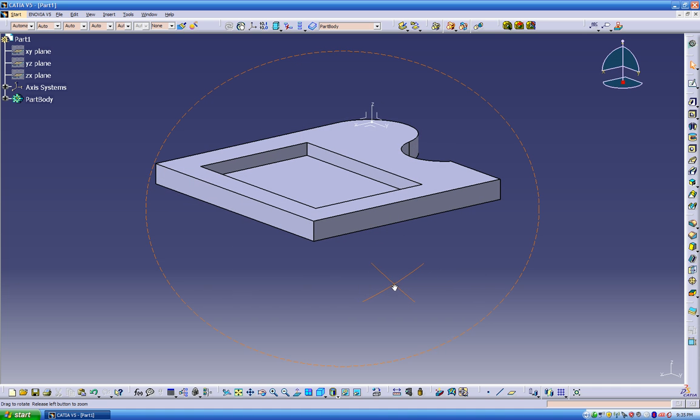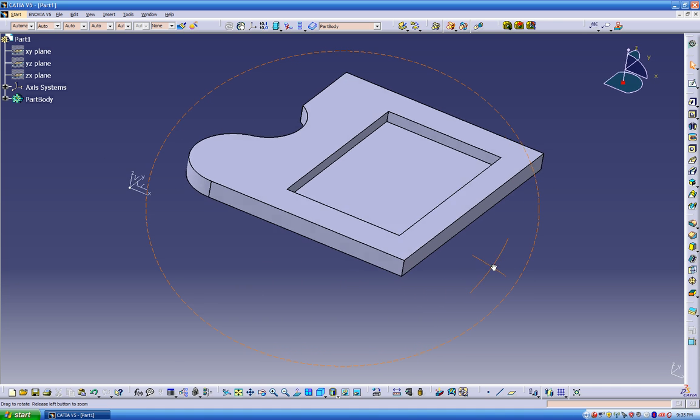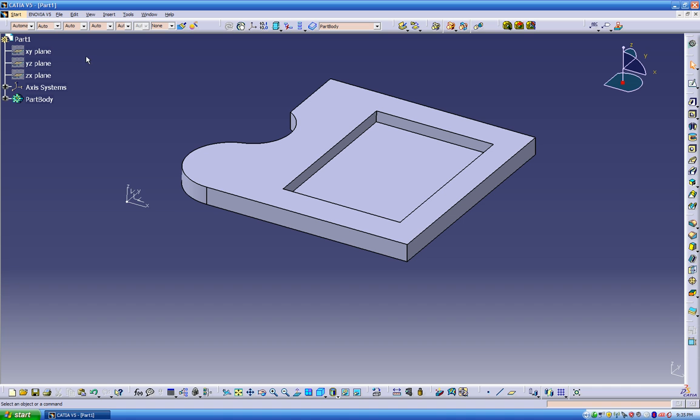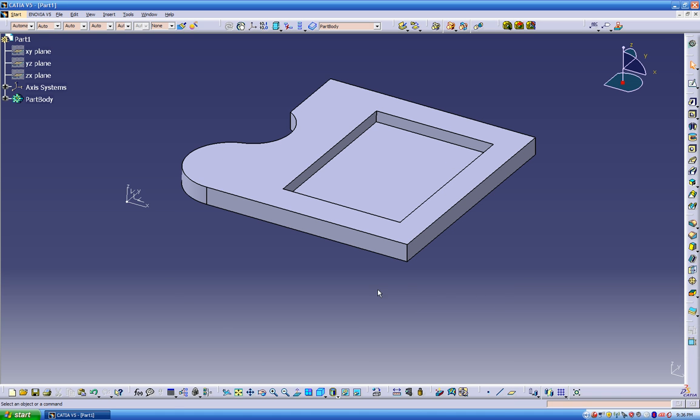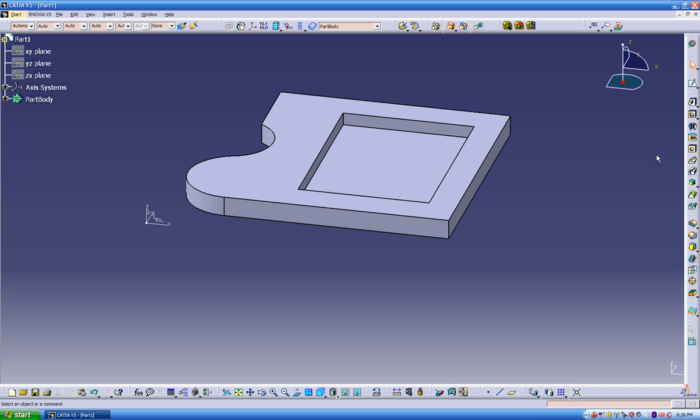And let's go back to our toolpath operation. Let's start advanced machining. Well, before we do that, let's prepare the clearance level, the clearance plane, and also let's prepare our block design. We want to make sure we have everything organized.